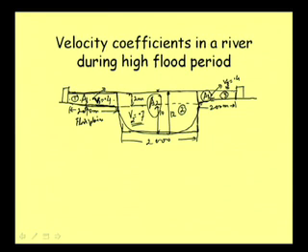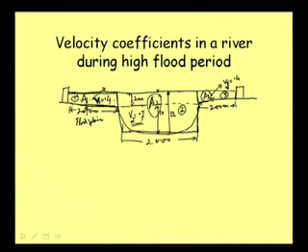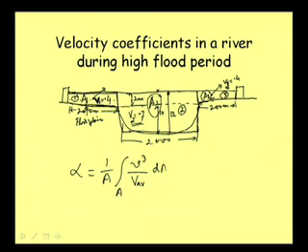Well, now if we then go to the alpha value, now we know the alpha, that velocity coefficient expression we can write as 1 by A, I am writing the conventional expression, 1 by A, then when we integrate it over the area we can write the average velocity V through a small section, then we were writing V average, and then we were writing this as dA.